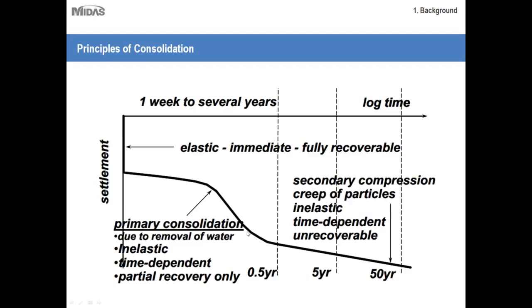And as far as how long it lasts, it really depends on several factors. It depends on the amount of static load you're placing upon your soil, as well as the clay properties themselves. But typically, it can take several years for full consolidation to occur. After which you have secondary compression, which, as I said, doesn't really have much to do with the drainage of water, but it has more to do with your soil compressing over time due to the constant static loads.